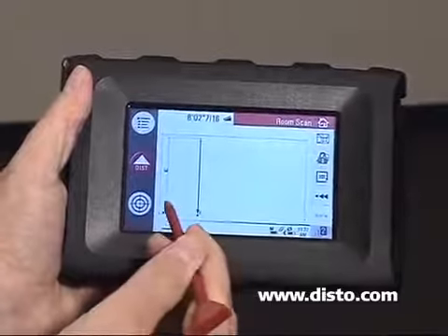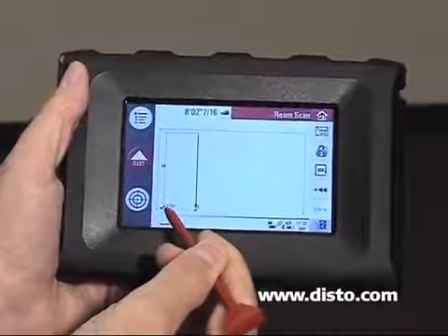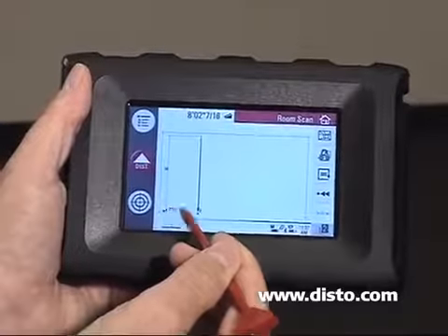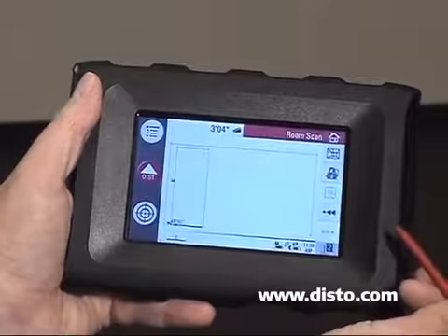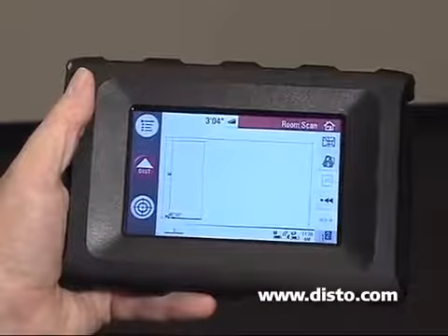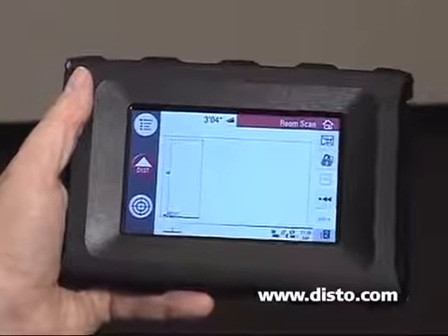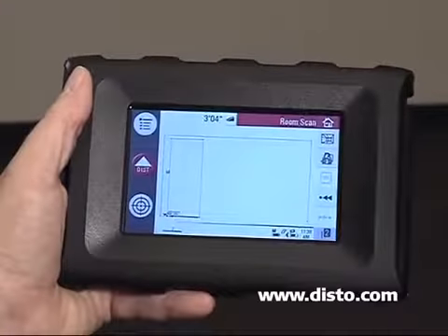You'll see that there's a bottom dashed line across the bottom of that box that we've just created representing our door. If we want to close that door up and have all 4 sides enclosed, we can go ahead and hit the close box symbol, which is the third one down on the right-hand side, and we've now closed up that entire door segment. So now we've located an initial door and the wall on that particular plane.